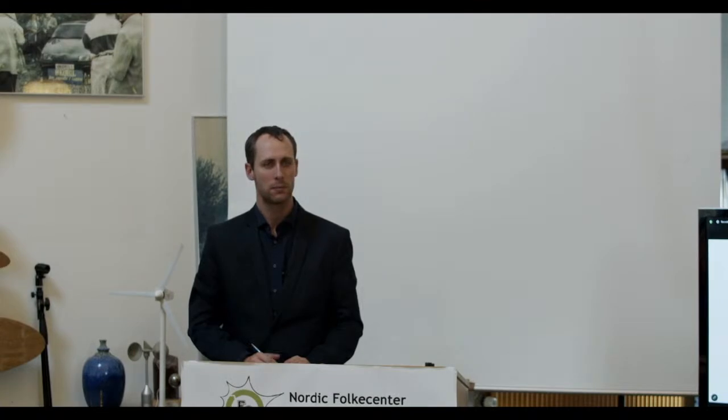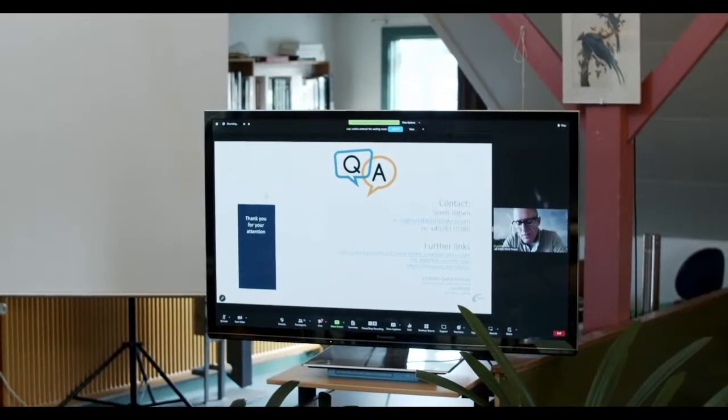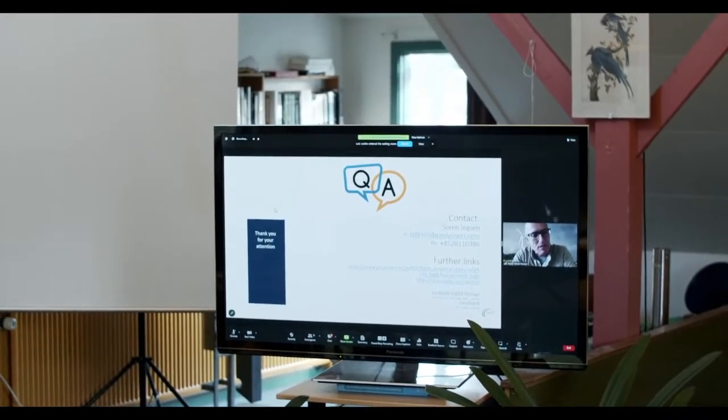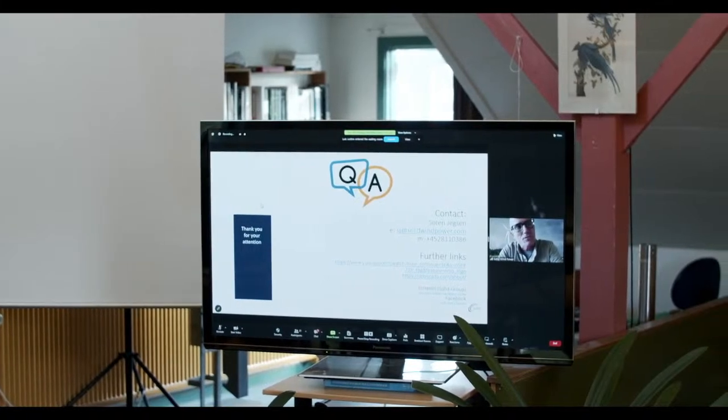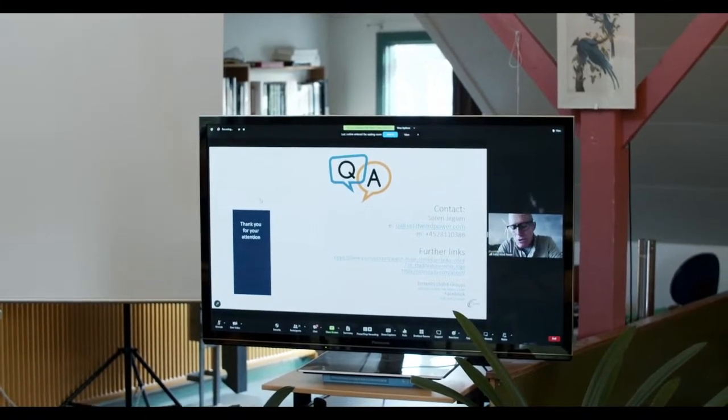I don't know how much time we have, but I do actually have some calculation I would like to show. In a very short manner, assuming we have 5 meters per second wind available, and assuming that the capex is around 170,000 euros for a turnkey solution, then the turbine will have an LCOE of just about 8.5 euro cent per kilowatt hour.